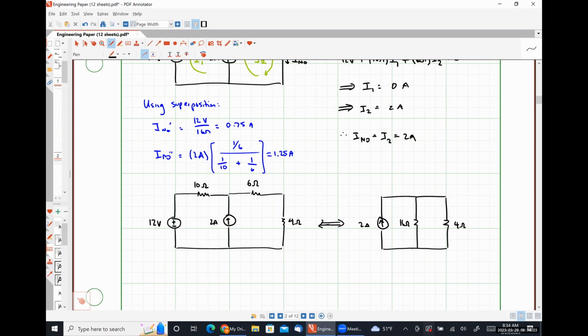Okay. So what should hopefully be ridiculously obvious here is that the Norton equivalent circuit and the Thevenin equivalent circuit are indeed equivalent to each other. So they are effectively each other's source transformation as well. Right. So if we ever have a Thevenin equivalent circuit, we can get the Norton equivalent circuit by simply doing a source transformation and vice versa.